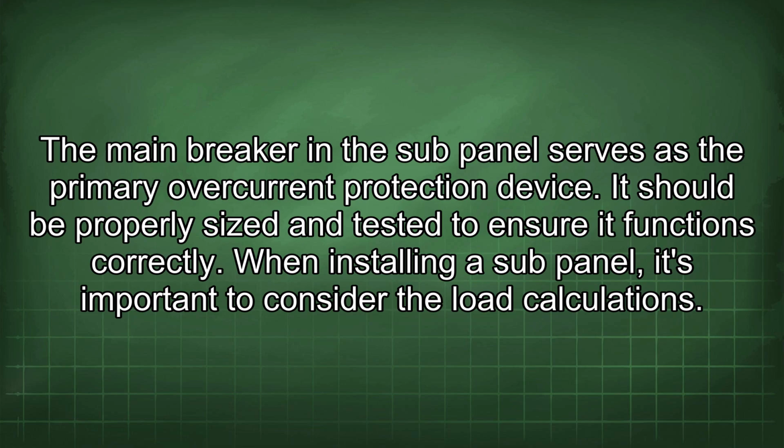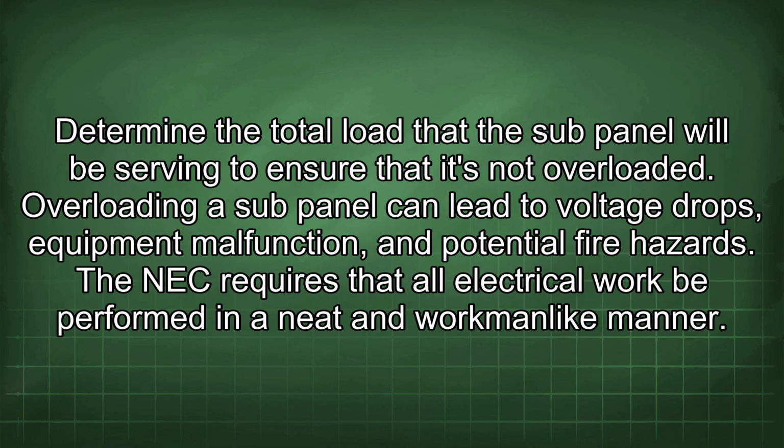When installing a sub-panel, it's important to consider the load calculations. Determine the total load that the sub-panel will be serving to ensure that it's not overloaded.